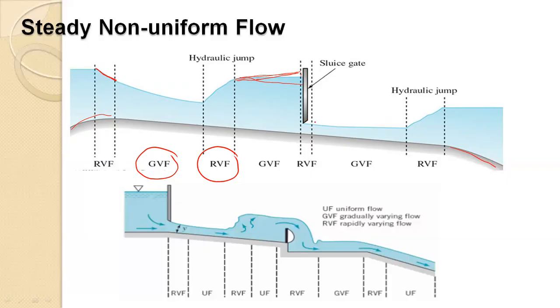And then when you have a sluice, of course, it obstructs the flow. Since you have a steady flow condition, here you have a flow Q, and the same flow should be occurring below the sluice. This would lead to very high velocities, but until it reaches some changes to the conditions along this slope, the water will flow at a particular velocity with a very small water depth. Still, the flow condition would be a gradually varied flow.